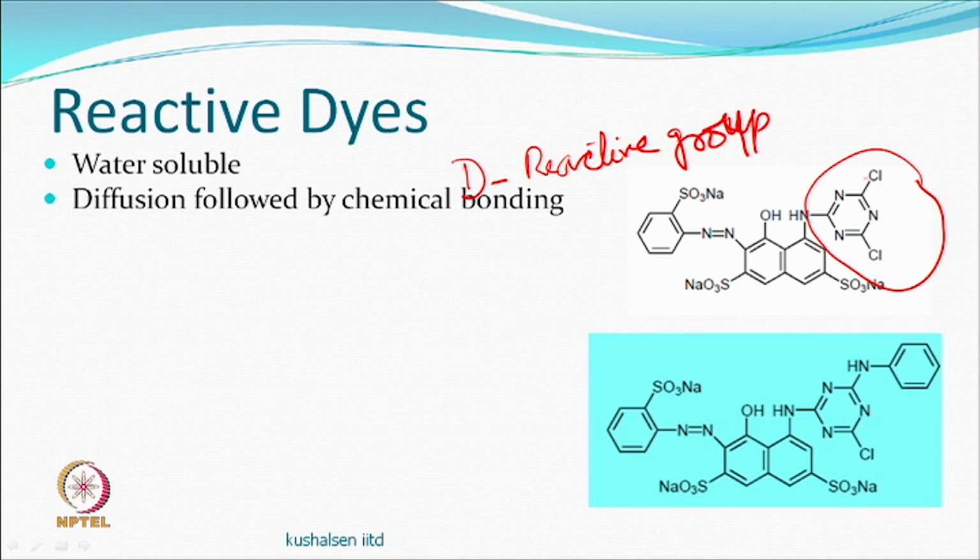This particular dye is called a dichlorotriazenyl system, sometimes known as the M type of reactive dye. This is not used for printing generally. It is too reactive, a lot of wrong things will happen, right thing will happen later. So, you want to create a condition, let us say it will fix at 60 to 80 degrees centigrade, then at room temperature it will not fix. So, whatever kind of material that you have, nothing will be happening at that time, it will happen at the right time.